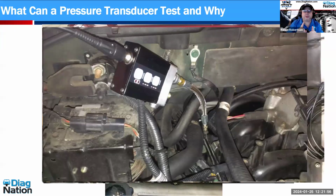However, I will tell you, in a V engine configuration where I'm plugged into this rail, but we know on the other side of the engine is another rail, there will usually be a massive difference in amplitude from one rail to the other. Because, as I mentioned before, from a pressure standpoint, you're going to read fuel pressure. That's not a problem. But the individual pulses per cylinder are going to typically decrease the further you get away from the transducer. In this case, heck, the other rail's on the other side of the engine.